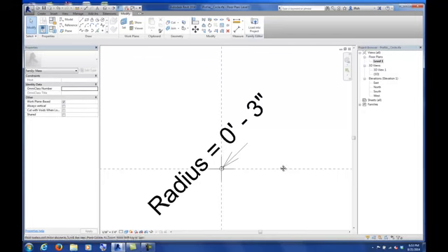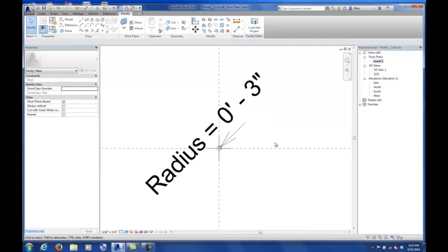In Revit, this is a very common task that we're going to be doing throughout the class, so I want to make sure you guys can master it, hopefully today. The way that we work is, since we're making all these different family types and we're going to be loading them into other file types, we keep that screen open and we open up a new one, and then eventually we can load into a project all these other things to start to embed them together.